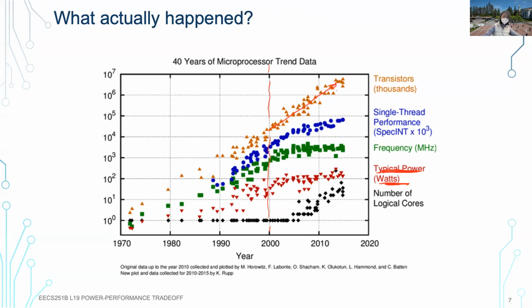And to minimize the power, one of the transformations or design decisions we made is basically to start with the multi-core processor. So we don't go to a super deep pipeline. We also cut the wire capacitance. We don't have a lot of long wires in our chip. All of those are designed to reduce overall capacitance and overall complexity, so that we can keep this particular fixed power envelope.